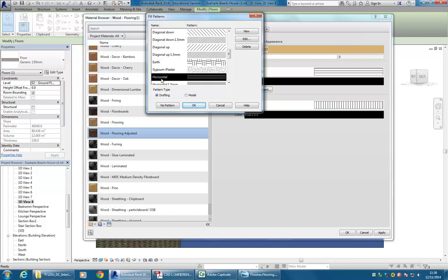And so here you can see it's got this name horizontal, which is obviously going to give us these horizontal lines, but it doesn't tell us the spacing. Even when it does, here it's got horizontal 1.5, it's not in real world units, it's in print scale. So when you have a size value like this, that's telling you the size that would print out. So these lines would print out 1.5 millimeters apart, and that's not a real world scale.